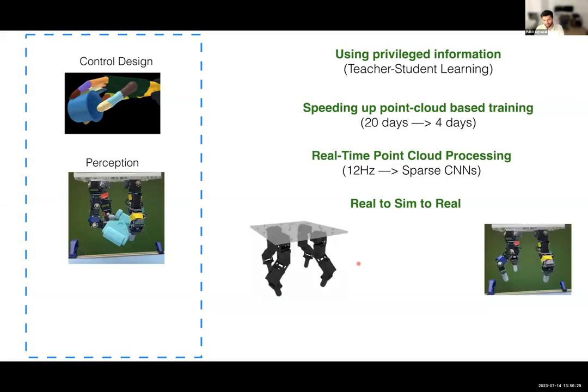For example, we have a manipulator in the simulation, we have a manipulator in the real world, but what are the lag of the motors? And without knowing the lag and the friction, the sim to real performance was quite bad. So what we did was system identification of just the manipulator dynamics, which really helped in getting high performance.